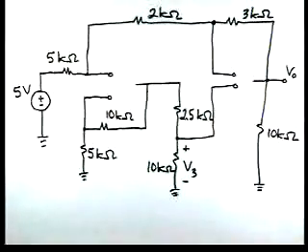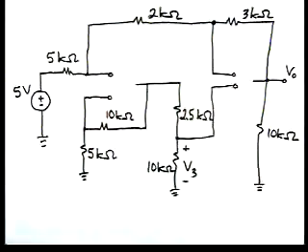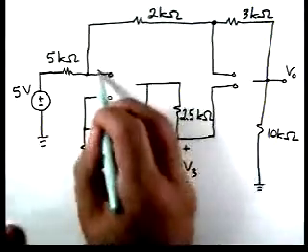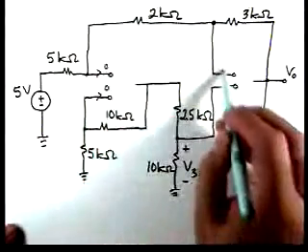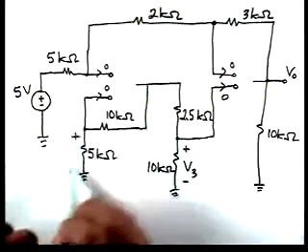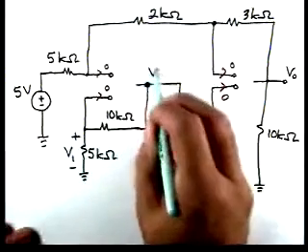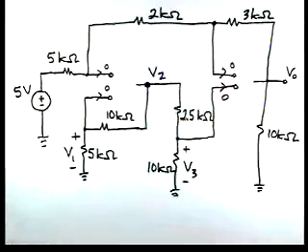So here's our circuit. You can see when we substitute the op amp model in, there's where the op amps were. We can see the current's 0 on these terminals. We enforce that by showing an open circuit. Now let's define this voltage as V1, and I'm going to define this voltage as V2.